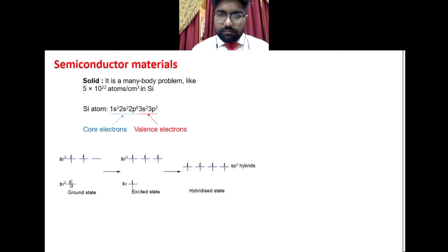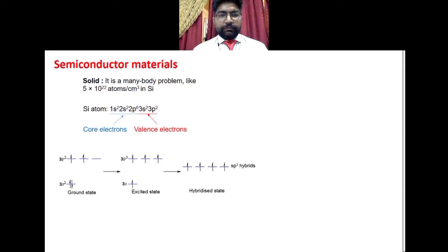You will not be able to measure it accurately, because we rely on V by I. When measuring sheet resistance, R sheet is equal to V by I. But if it is a non-linear contact, then it depends on the voltage, so V by I will keep changing for the same material. We will never find the accurate value of the sheet resistance, and without it you will not get an accurate value of the resistivity.